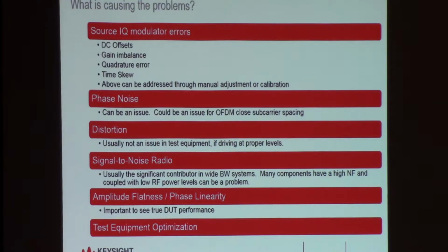And we need to make sure through the whole process we're preserving the signal to noise ratio, because once noise gets into the system, you can't get rid of it. And as I showed in that picture earlier, where we had that elaborate setup to do some of those extremely wide bandwidths at the high frequencies, you can imagine there are signal levels that could be adjusted up or down at each of those stages. And if you give up dynamic range earlier in one of those stages because you don't have something adjusted right, you're not going to get that back. So this is an area to always be aware of and concerned with.